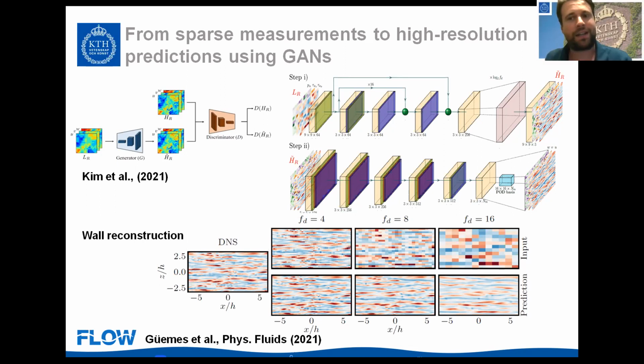Exactly, so I understand your question. You don't measure it directly. You have a sensor from which you can infer that quantity, as the equivalent of the hot film for measuring the wall shear stress. But I see your point. You also have an uncertainty there that is associated with the evaluation of the model of that sensor. Yes, so it's not perfect at all.